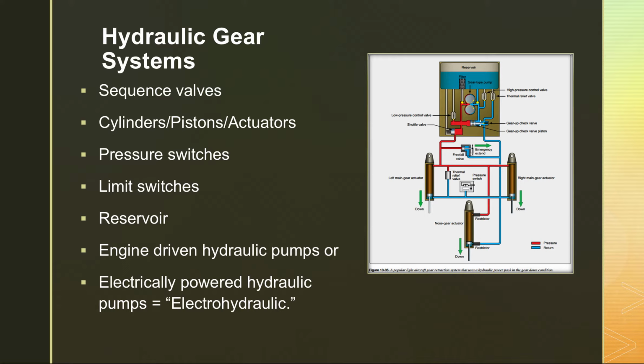Pressure switches usually have a high pressure switch so the pump knows when to shut off, or a low pressure switch so it knows it needs to turn the pump on, or some way to keep pressure between those two values. The reservoir is just where that fluid is stored. Usually there's plenty of fluid that'll fit in the lines. We bleed all the air out of them, and then plus extra. Need to know where this reservoir is and know how to pre-flood it to make sure there's enough in it. These systems do leak, and so they will need to be checked periodically.